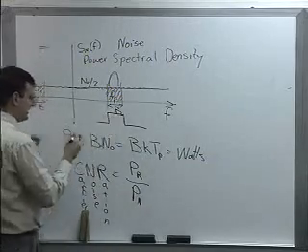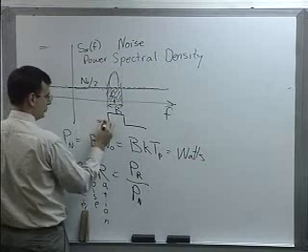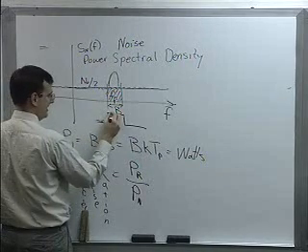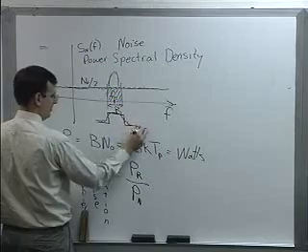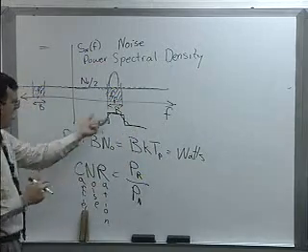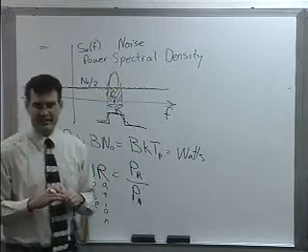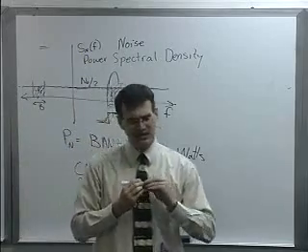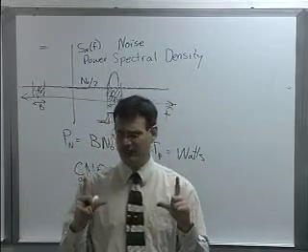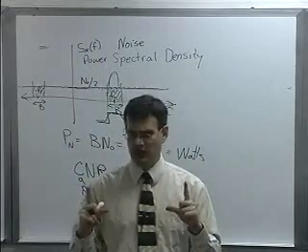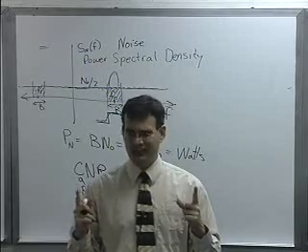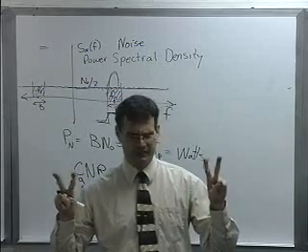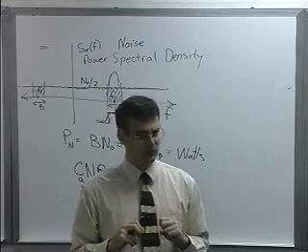In fact, usually you've got something that has ripples, then a smooth transition and some more ripples out of band. And so oftentimes when you talk about noise analysis, that B that they talk about is not always the physical bandwidth of the system or of the signal. It's what they call the noise equivalent bandwidth. You'll see that term used sometimes in the book.